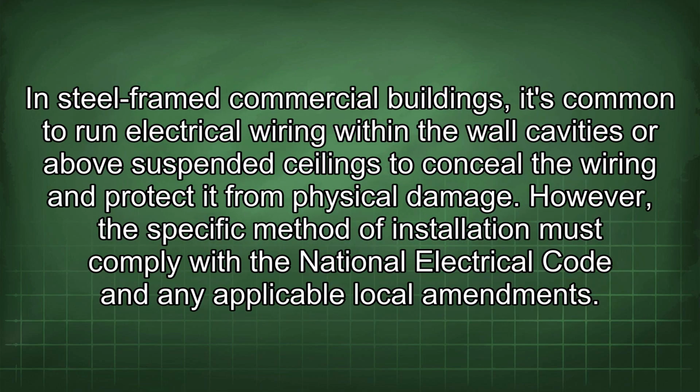In steel-framed commercial buildings, it's common to run electrical wiring within the wall cavities or above suspended ceilings to conceal the wiring and protect it from physical damage. However, the specific method of installation must comply with the National Electrical Code and any applicable local amendments.